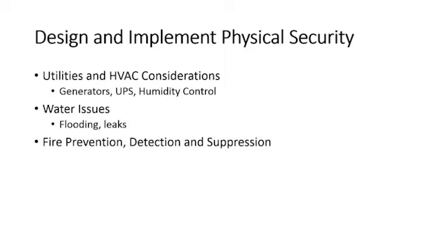Depending on the UPS size, I should say, most of the ones you get for your desktop servers will keep them going for 30 minutes, 45 minutes, an hour maybe. That allows you to get there and shut it down properly so you don't have data corruption and broken sessions and just bad things that could happen by jerking the power out of your server.